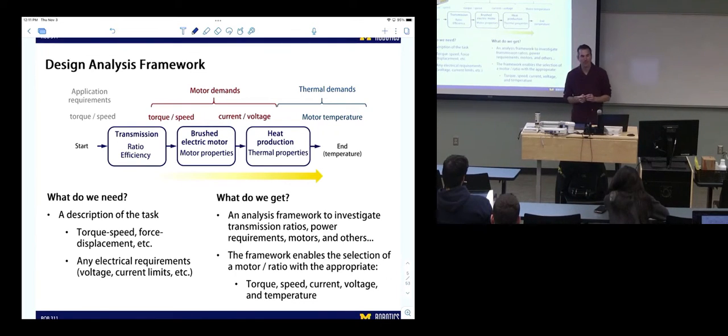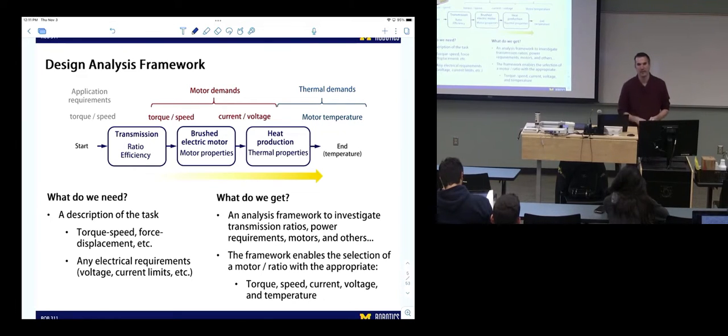Where might the current limits come from? What sets current limits? Yeah, be the resistance in the circuit or whatever. Yeah, so the current limits come from the heat that's generated from the resistance, and that could be both on the motor side, where the motor could get too hot, but also the drivers will have their own limitations.